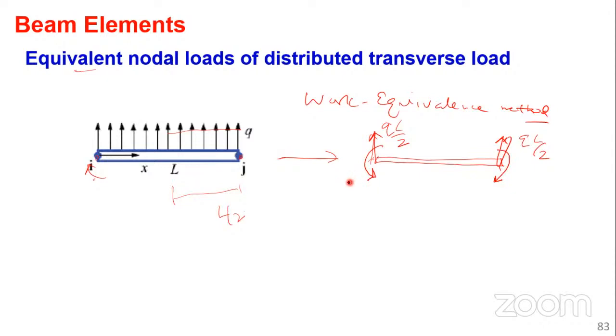So this will be QL squared or WL squared over 12. So why this sign convention? Remember, when you look at the way these loads are applied, they cause the actual reaction, it causes the bending like that. It causes the beam to hog, not to sag, right? If the load was applied downward, it would cause the moment to sag.